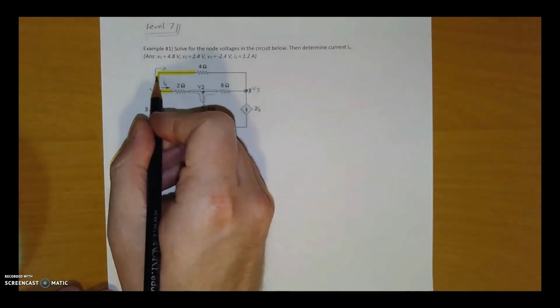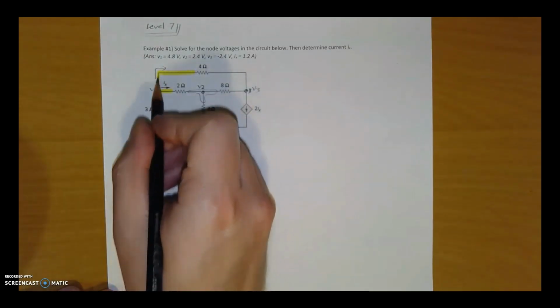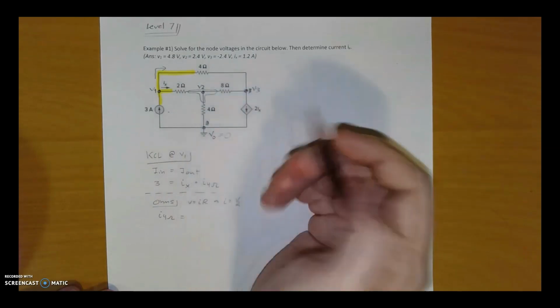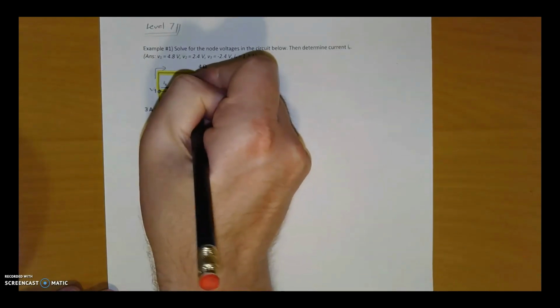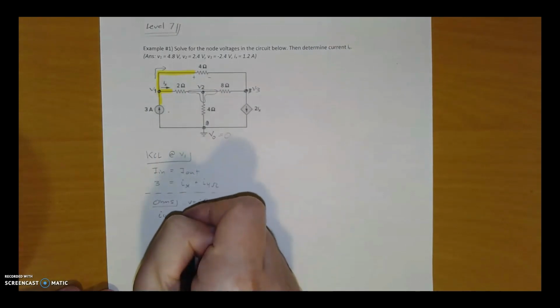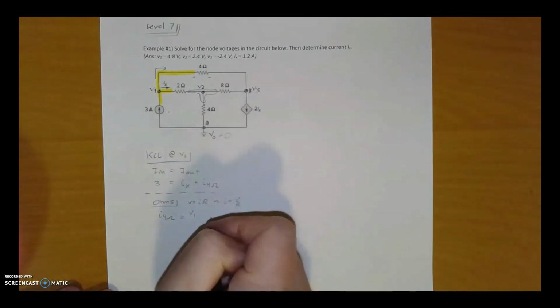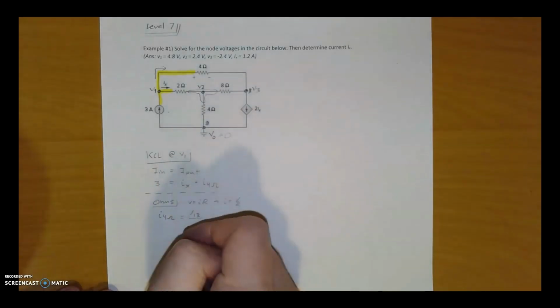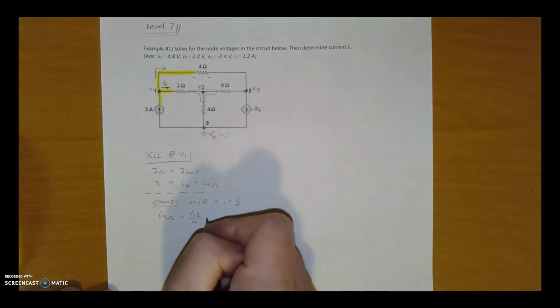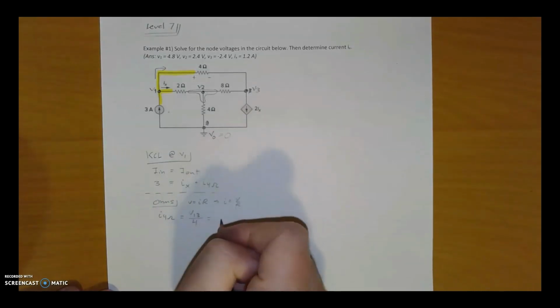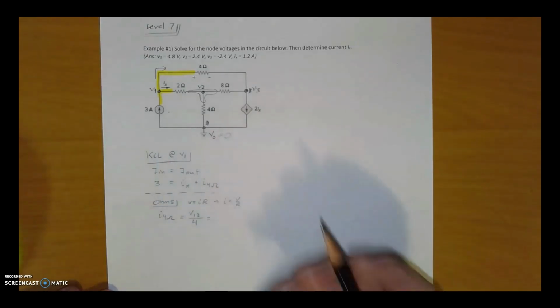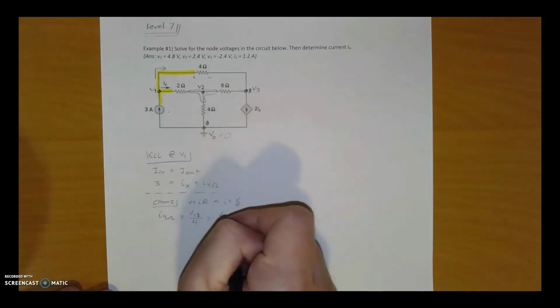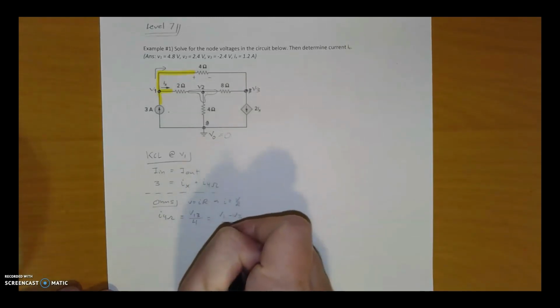And so notice the arrow. It is from V1 to V2. If you did passive sign convention over here, you'd have a plus minus. So this is the voltage from 1 to 3, or realistically, it's the voltage of 1 compared to 3, and over the resistance, which is 4 ohms. You can expand that now or expand it later. If you want to expand it now, it would be V1 minus V3 over 4. And that's what you'll sub in up here.